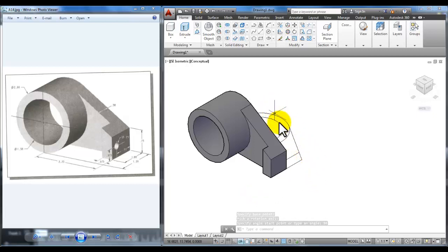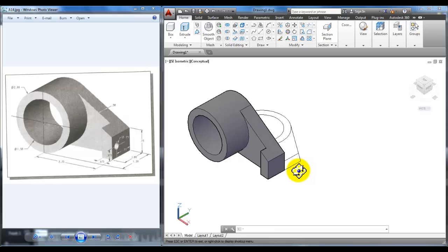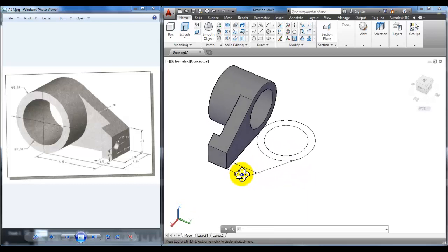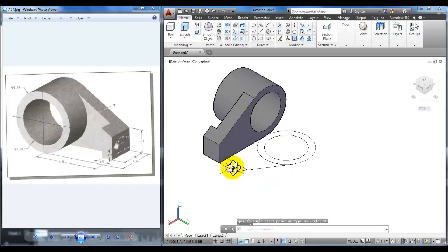And you'll see that when you work with press pull, the original lines are actually still left behind. With press pull, it doesn't consume the line work. It is separated. You can hold your shift key down, press the wheel of your mouse, and orbit to the other side.